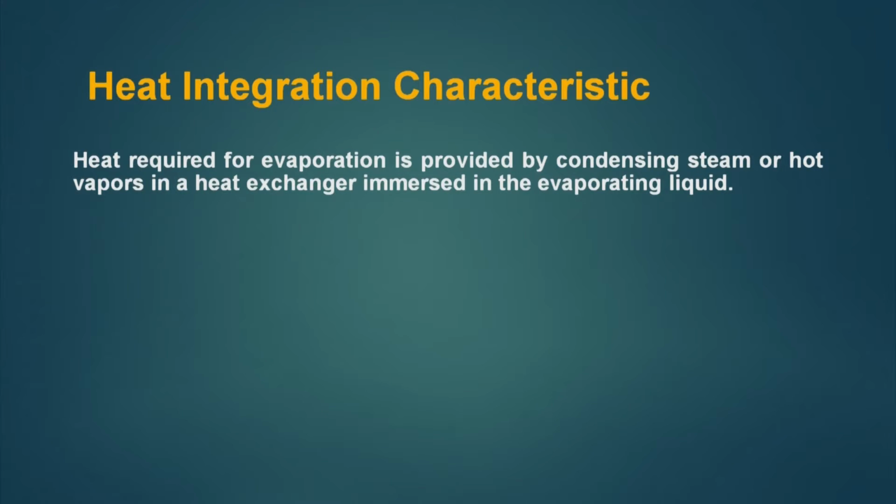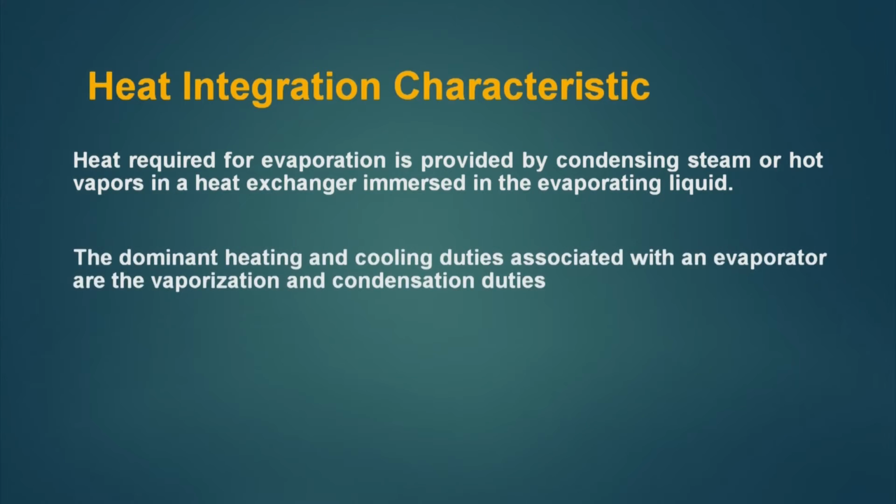Heat required for evaporation is provided by condensing steam or hot vapor in a heat exchanger immersed in the evaporating liquid. The dominant heating and cooling duties associated with an evaporator are the vaporization and condensation duties.